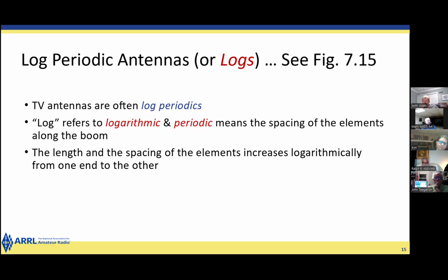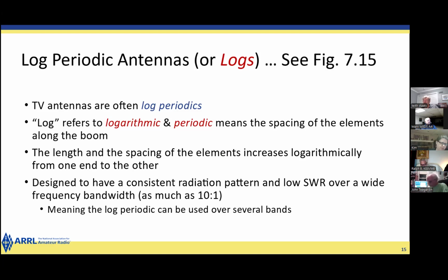The length of the spacing increases logarithmically from one end to the other. They're designed to have a consistent radiation pattern and low SWR over a wide frequency bandwidth, as much as 10 to 1. So it's a multi-band antenna.